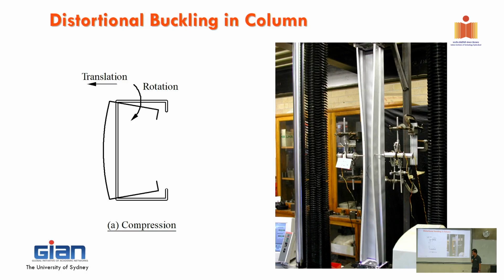What if, say for example, this is 5 meters, and if it is 10 meters, then you have first like this and then like this. At 5 meters there is no deformation as such because it is changing sign. If I keep a knob there, will it be the same or different? Good question. If you put that in, it means that you eliminate the flexural torsional buckling.